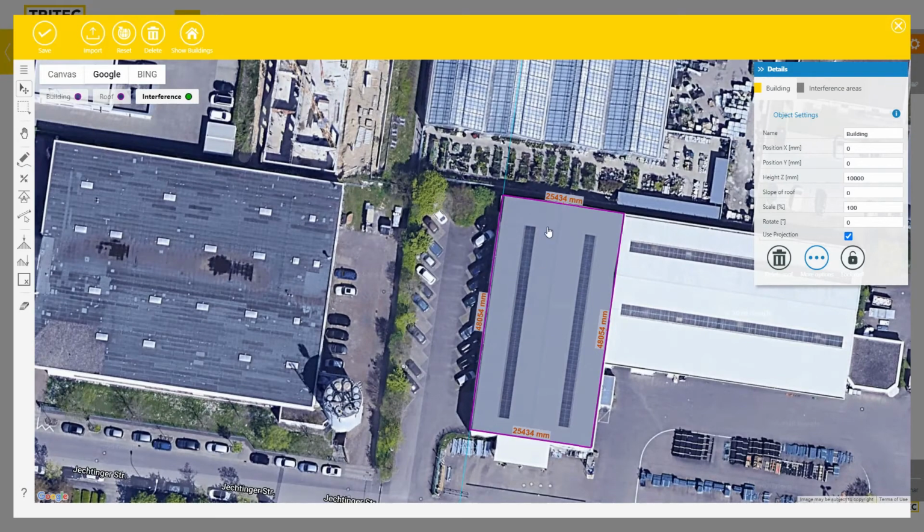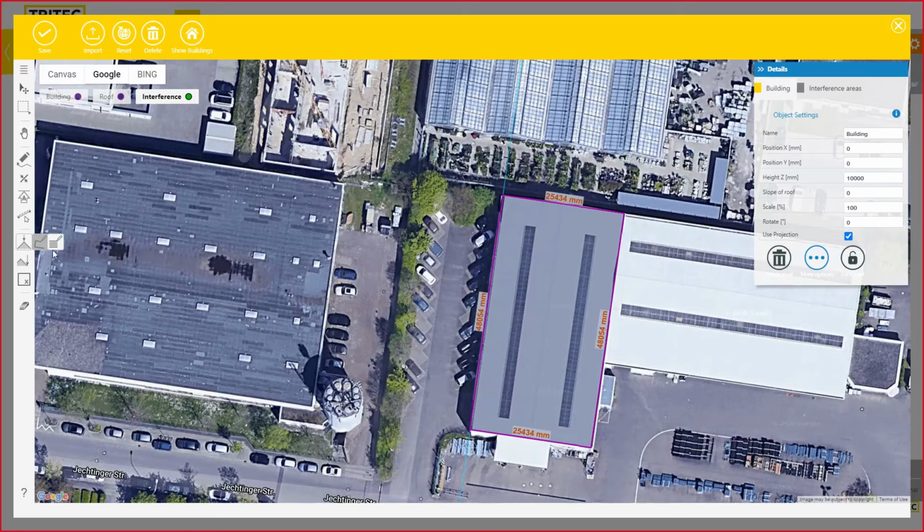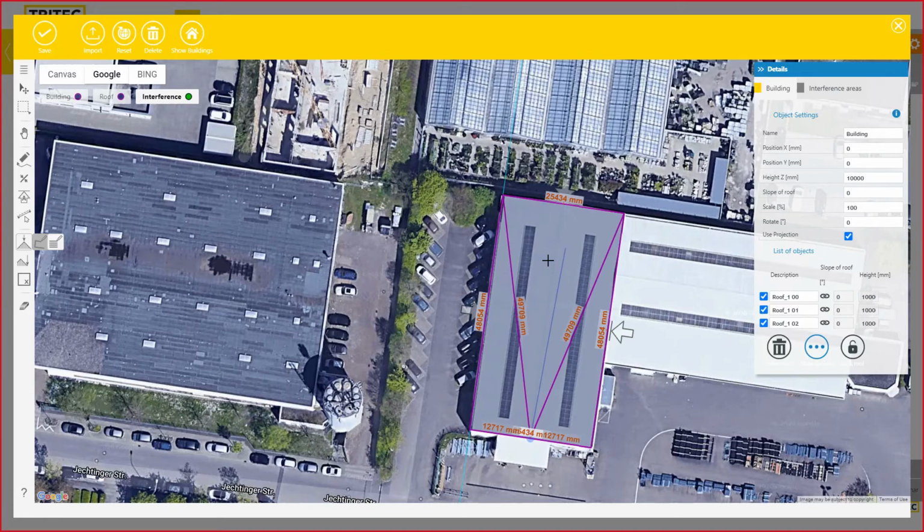As it's not a flat roof, it's a pitched roof, and it has a ridge here. So this is the ridge tool. And I just want to draw one ridge and not a couple of ridges, so I don't have shed roofs, just a single ridge. So it's auto-selected here. And you see there's also a snapping mechanism in the exact middle of this line, which I'm using. And I could also hit and keep the shift key on my keyboard. And you see I could only move parallel now to the guideline, and it's also snapping to this line here.